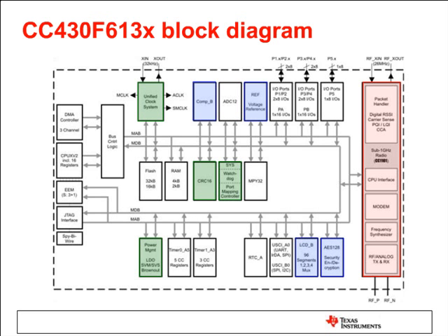So it's based off of the 5XX core, and so you have a 5XX core logic there. And I'm going to start from this green box there at the top and kind of work my way around the circle. Unified clock system. The MSP430 clocking system is the same as any other previous 430 clocking system. You've got 3 clocks. Your M clock supplies the CPU. Your SM clock is kind of your fast peripherals, and your A clock is your slow peripherals, or your 32